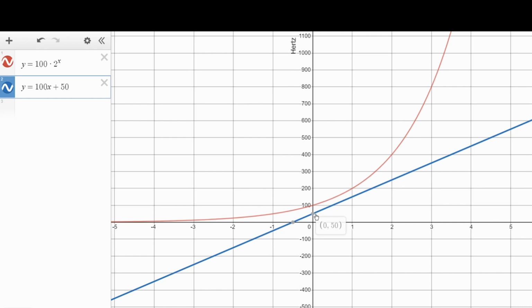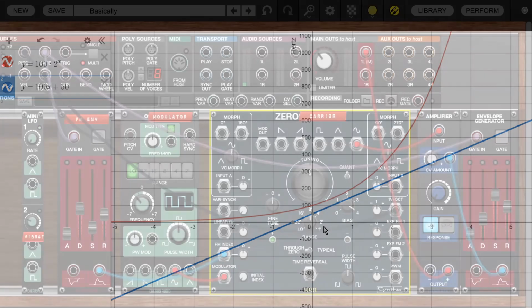So this represents 100% modulation. You can see as the bias goes down and down, the value that represents 100% gets tinier and tinier. So when we put in big modulation signals, we get a huge range in the percentage of modulation, and that's why it sounds gnarlier. The modulation sounds gnarlier with lower bias.